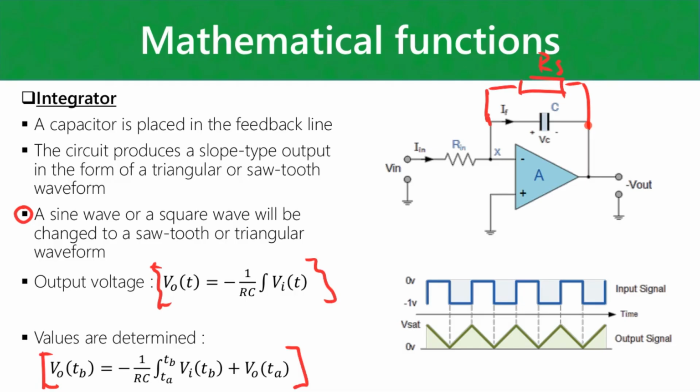So this is also to limit the gain. Whereas the differentiator had a problem with high frequencies, and increasing the gain at high frequencies, the integrator has the opposite problem. It tends to significantly amplify DC and low frequencies.